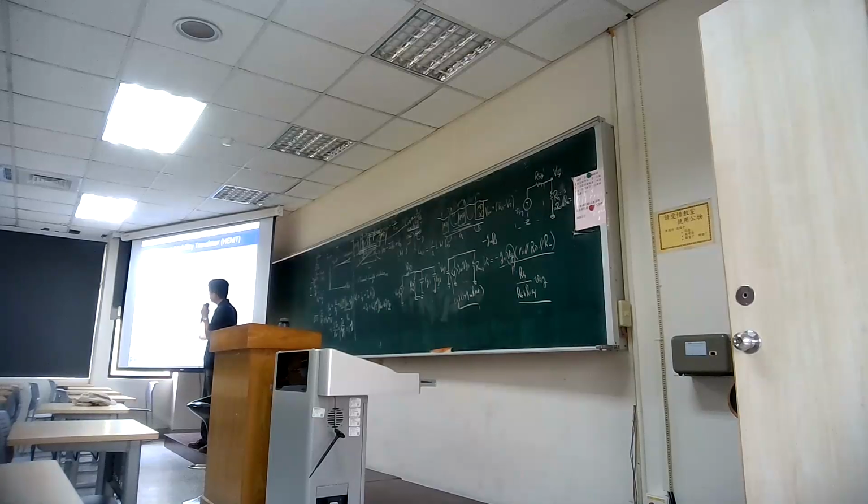So the idea is that if you join two different semiconductors, like the GaN layer and the AlGaN layer, you can increase the carrier population or carrier density, trying to form a trap in between the heterojunction. Okay, so you can consider that by connecting two N-type semiconductors, there will be a trap between the connection. And there will be a certain discontinuity between the conduction band and the valence band. That's what we call the two-dimensional electron gas.